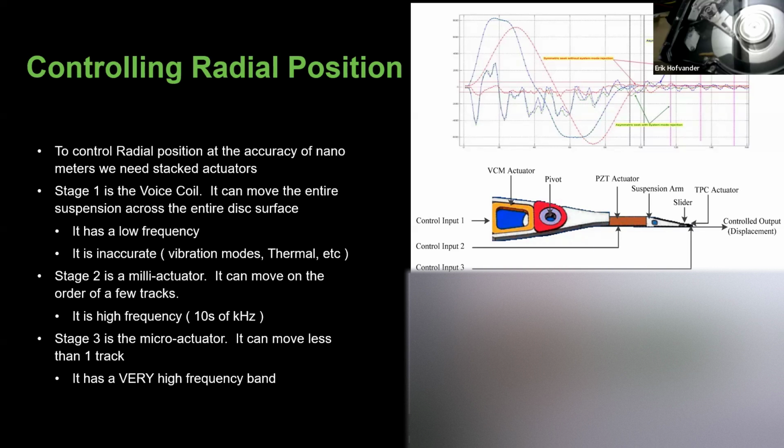Here you see an image of a modern actuator. So here's the main actuator. The VCM is so large, I've not pictured it here. You'll next have these milli actuators. These are PZT crystals, so as I apply a voltage to them, they are going to change in size. Now that's going to give me